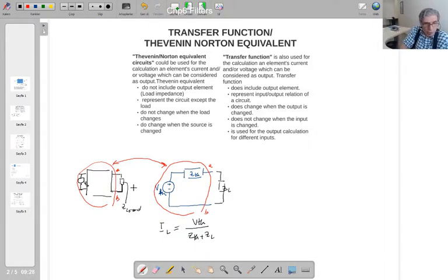But the Thevenin equivalent that I found here is the circuit's Thevenin equivalent except the ZL load, isn't it? So this ZL element, although at the beginning it is within the circuit, I put this out and find out the equivalent of the rest of the circuit as the Thevenin equivalent circuit. By using this Thevenin equivalent circuit, I can calculate the current and voltage of the element that I have chosen as a load or as an output element.